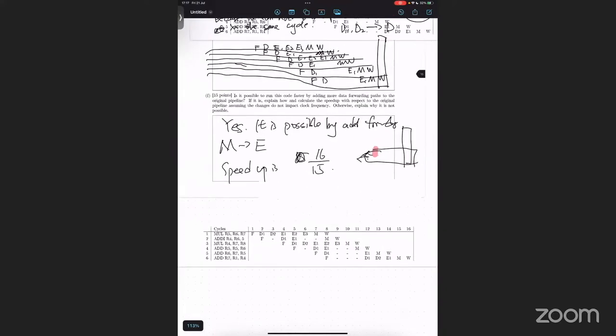So you're referring to the original pipeline diagram, right? So yes. Can you say again, which instruction are you looking at? Yeah, instruction 2. We are finished with the execute stage because it's an add instruction. But then we have to wait 2 cycles. Yes, it's because it's an in-order pipeline. So yeah, you have to wait before the previous instruction has released the stage you need next. Okay, thank you. Yeah, no worries.